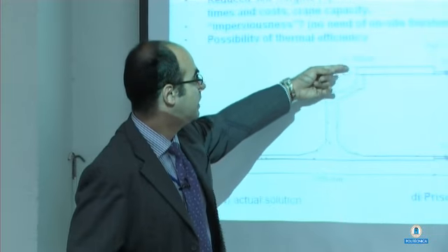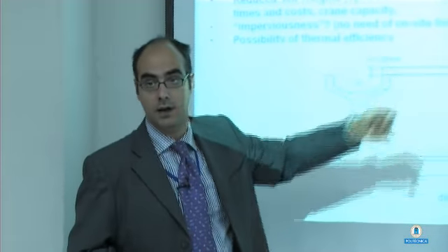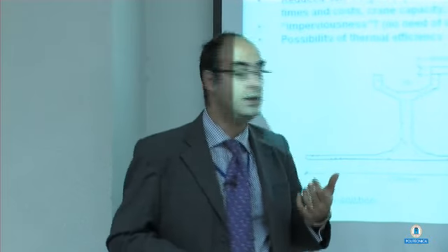But still there is a very good advantage, because basically you go to 1/3 of the thickness, and you surely have a very much lower self-weight, which also means that you can better design your supporting structure. You probably need a lower capacity crane for construction. So there are several benefits.